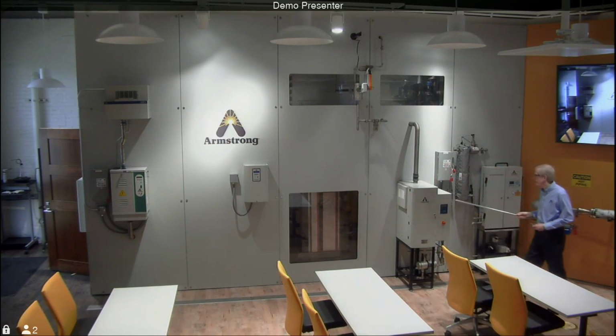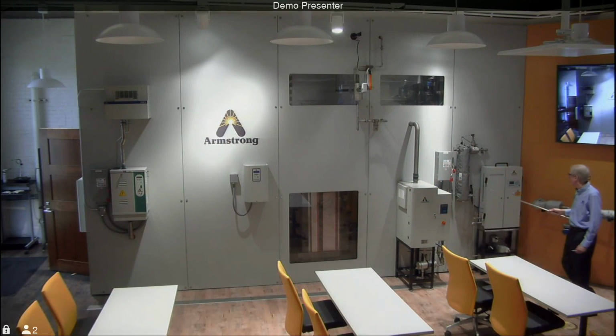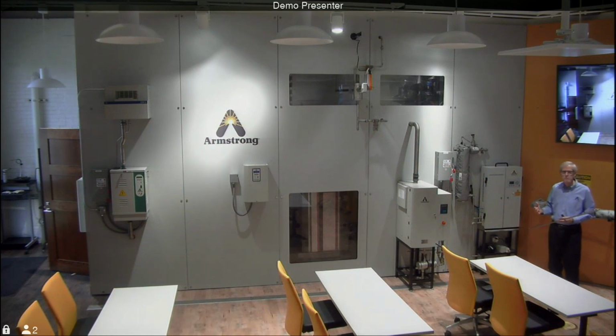And then as we move toward the corner, we have a steam quality monitor. And this steam quality monitor has the ability to identify the dryness fraction of steam, the amount of superheat present when you drop the steam pressure to atmospheric pressure, as you might in a sterilizer or autoclave, and any amount of non-condensable gases concentrated in the steam itself.